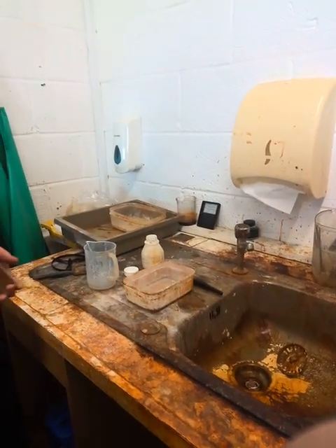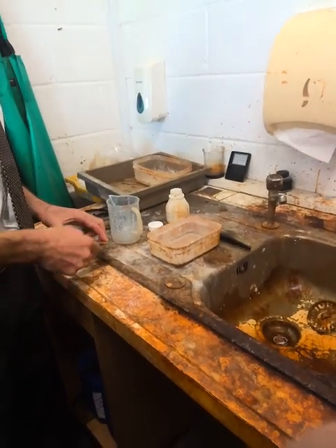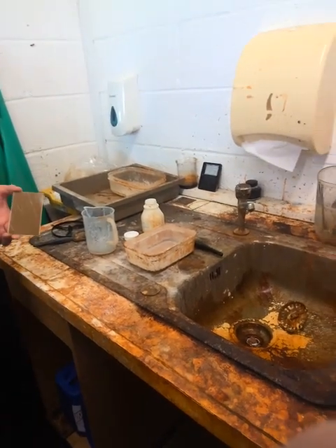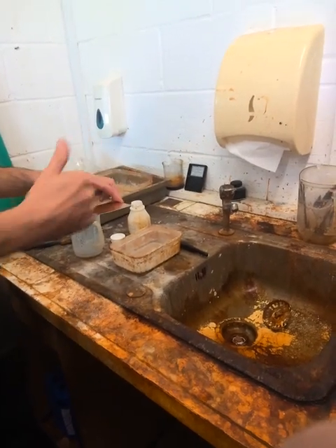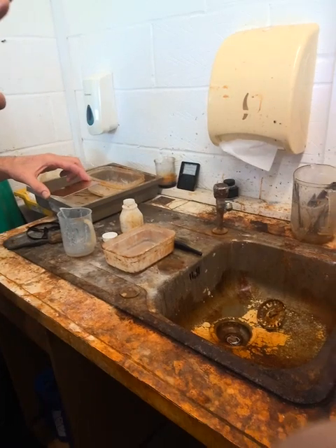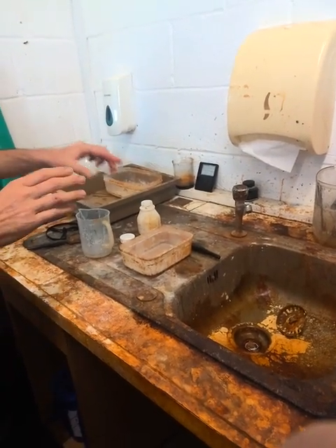Agreed? What you do is you put your piece of PCB into this, and what will happen as you rock this backwards and forwards, over about a minute, you'll start to wash away those areas that have had the UV rays exposed to them, okay? So any area that's been exposed to UV rays will wash off.